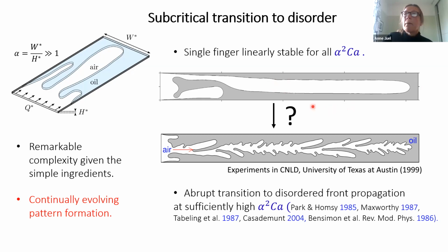And there's lots of interesting mathematics to be done in that limit. But from an experimental point of view, we operate at finite capillary number, and we'd like to understand the pattern formation in that intermediate regime where surface tension is finite. An interesting observation is that in practice in your experiment, you get this finger that is steadily propagating, and then you keep on increasing this Saffman-Taylor parameter.